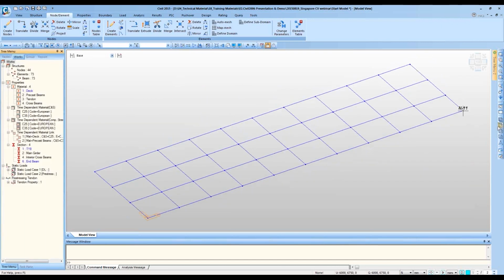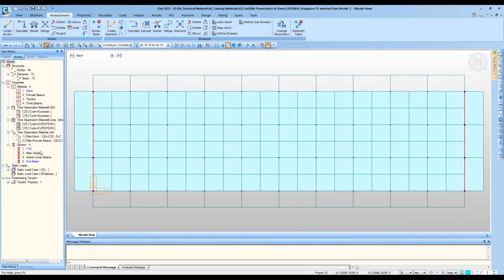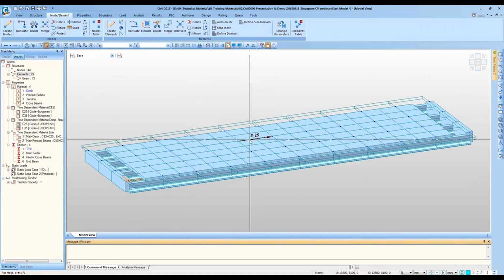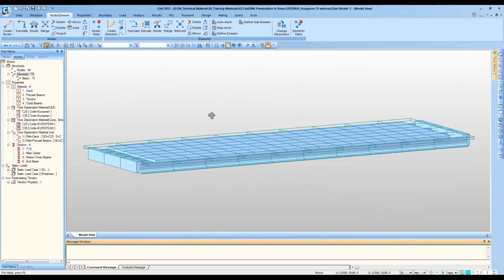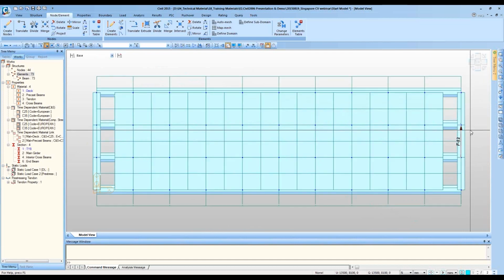After that, let's say I want to have a different section property for this end beam. In this case, how can I do that? Simply drag and drop, that's all. So I want to assign them to this section property. Drag and drop. The section will be automatically changed. So generation of such a bridge is very simple and easy in MIDAS 7. So the geometry has been completed.